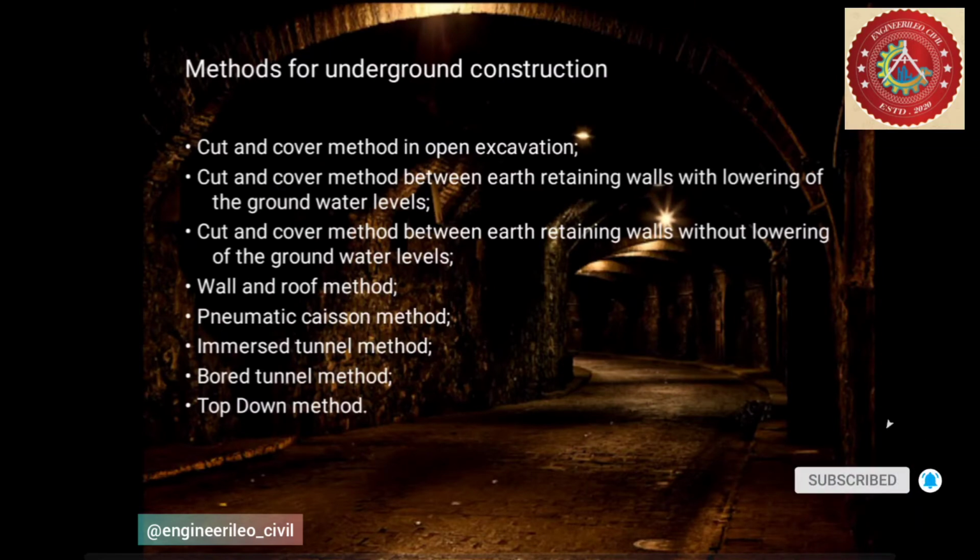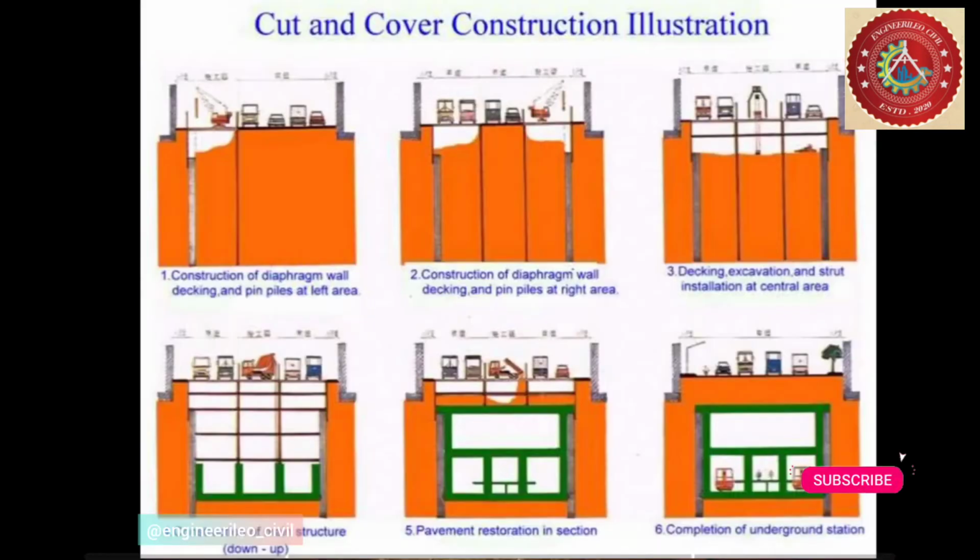Some of them are specifically the cut and cover method in open excavation, the cut and cover method between earth retaining walls with lowering of groundwater levels, the cut and cover method between earth retaining walls without lowering of groundwater levels, the wall and roof method, the pneumatic caisson method, the immersed tunnel method, the bored tunnel method, and the top down method. Okay, now first the cut and cover construction illustration.